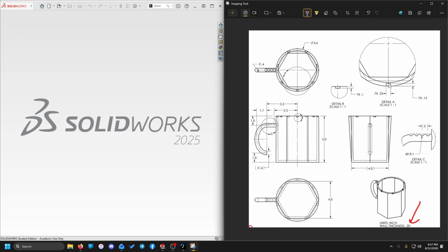Then we've got these little notches around the rim of the cup. Looks like there are 7 of them based on our note. And then we have a handle sprouting off the side. This looks like it would be a pretty easy sweep feature, just because we've got a consistent diameter of 0.4 profile that follows through that entire shape. And then we've got a couple little notches carved into the top of it as well. So that we can probably do a linear pattern. Once we've got one of them, pattern to get the rest. Cool. So, gives us a bit of a plan of attack.